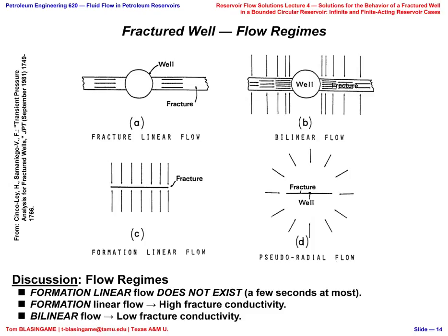What's a negative of having a higher choke, class? Remember all that sand you pumped in? It's coming back. Okay. Some companies have a strategy, just to hell with it, we'll produce the sand. Some companies don't want to produce the sand. Some companies have tried sand mitigation, etc. There's other issues as well. When you open a well up, what does it do to the stress in the formation, especially near the well?